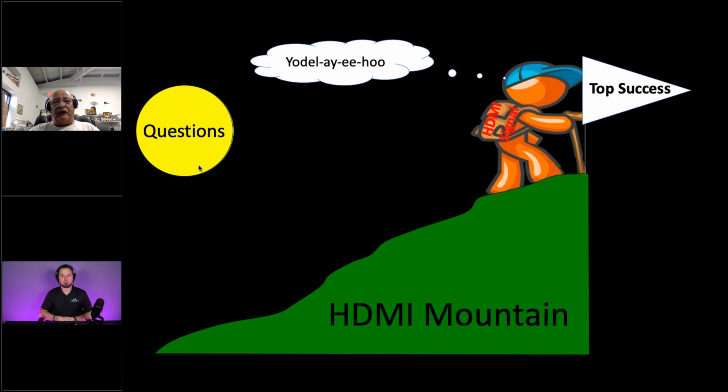Now a lot of these AOCs have gotten really good. They're getting down into the mid 60s. Not good enough, but in another, I don't know, 6 months, HDMI is changing the rules, which is going to save a lot of us a lot of problems. They're upping it from 55 to, I think, 320 milliamps. Oh wow, that's a big jump. So that'll solve all these low current issues.